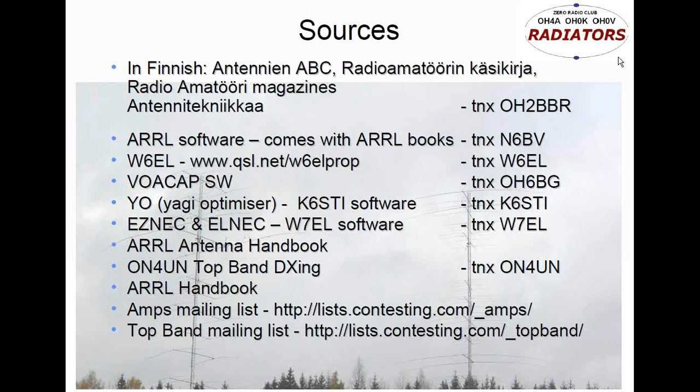Yes. So on 10 meters, we can buy RG213 in Europe at a cost of about €2 or $2.50 a meter. So it's about $1 a foot. So if you can find hardline at double that cost, it's a great deal. If you can find hardline at 4 times that cost, then it's a bit there and there, but it's a cost matter.